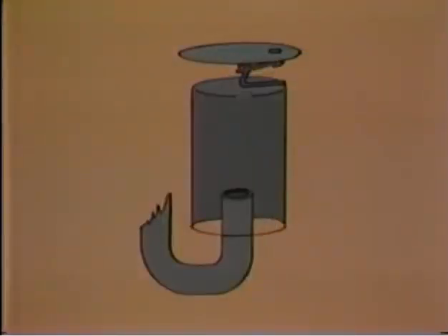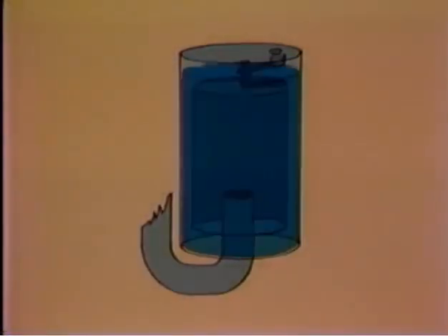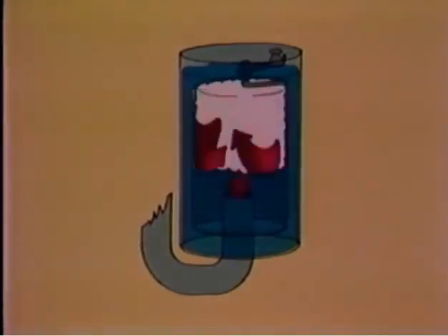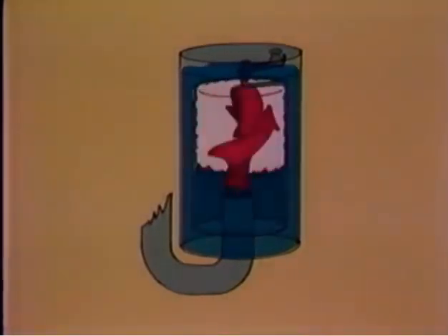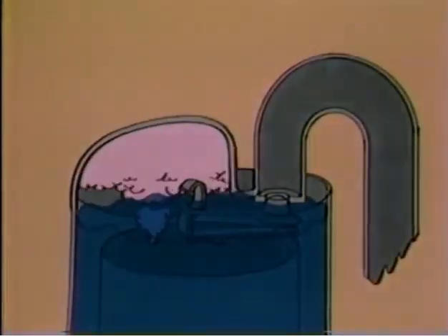The body of the trap is a cylinder which contains the bucket. During proper operation, this cylinder is always filled with condensate to a level above the top of the bucket. This condensate provides a constant water seal above and around the bucket, preventing live steam from escaping from under the bucket. Finally, in the cap of the body is a space above the water seal where any non-condensable gases which have passed through the bucket vent will collect while the valve is closed.